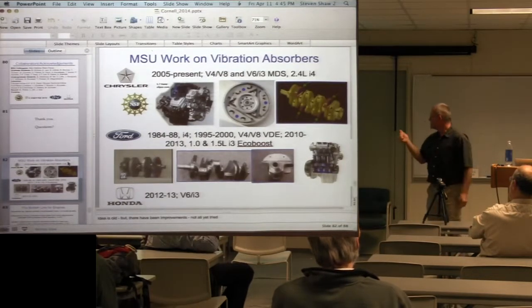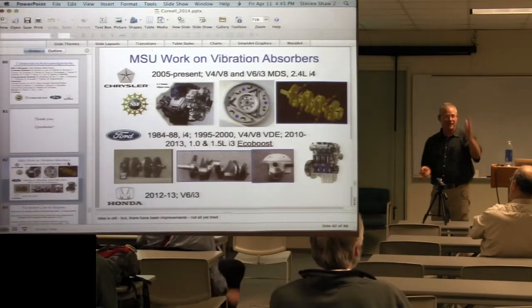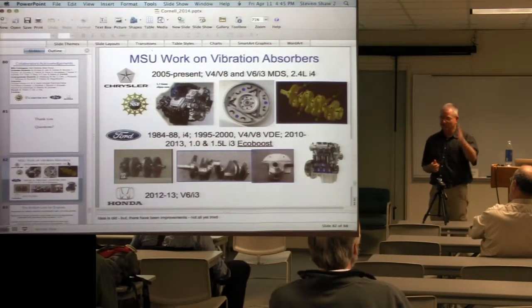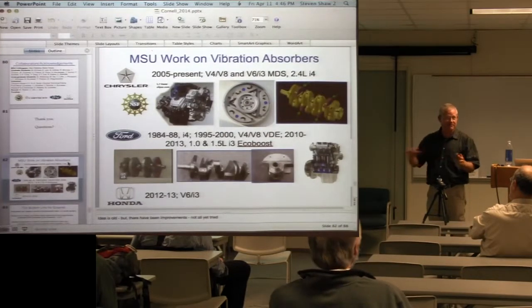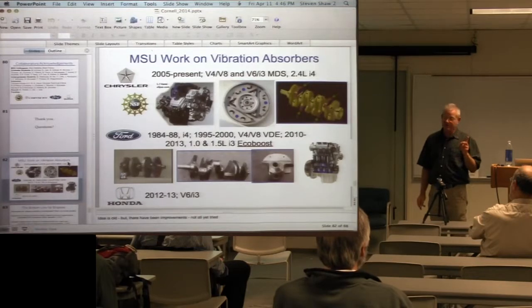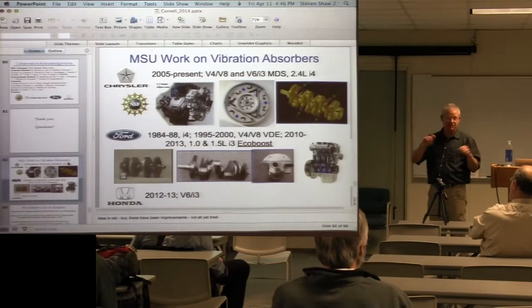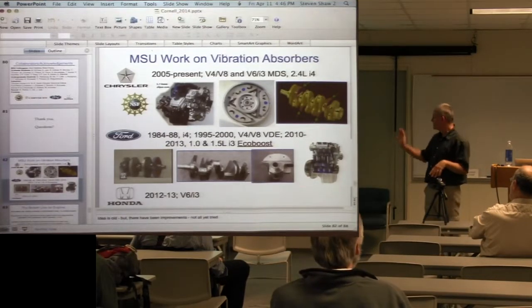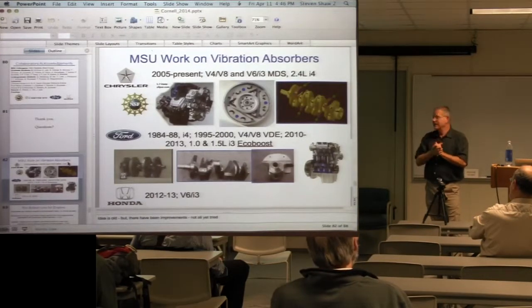It could be. The one interesting thing about these order tuned things is that when you have an engine with N cylinders, 4-stroke engine, the excitation order is fixed. That's just it. Now, that's not exactly true, it's dominating. It has some other harmonics, especially if you have cylinder misfires, you get things at half orders, but they're very small.